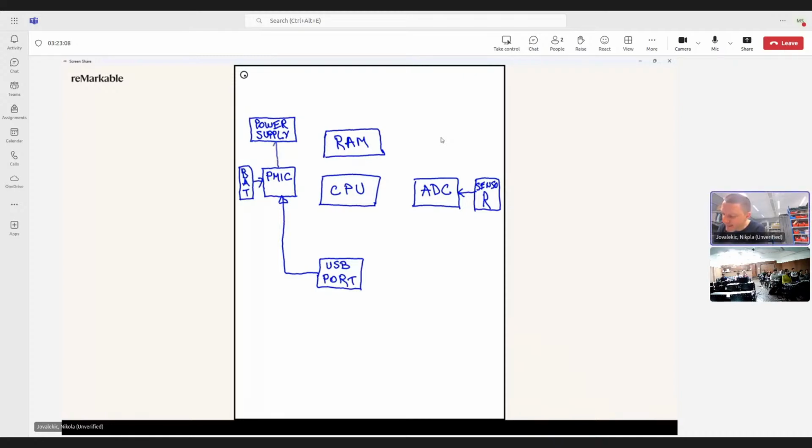And then we come here. So that was a good observation. We need a PMIC which will arbitrate between this guy here and this guy here. And when this PMIC finishes its job, then we will deliver a stable power supply to our power tree, which further delivers power to the whole board. This is a good thing. If I were you, I would do this part as the very first thing, for example. But okay, this approach is also good. Let's continue.